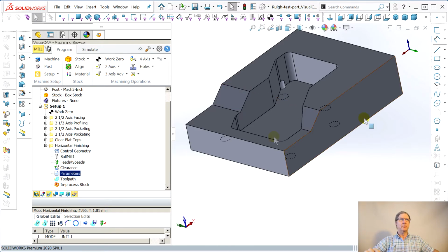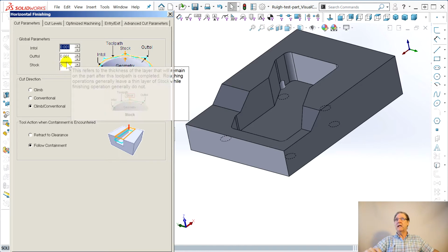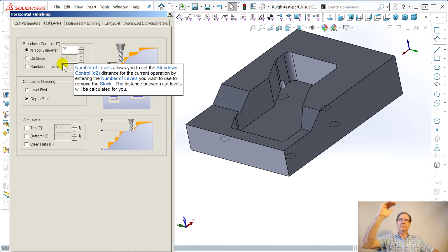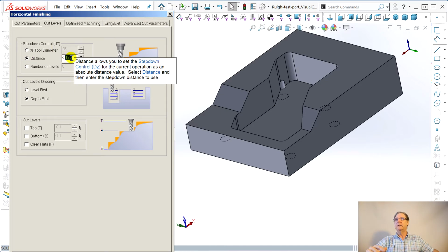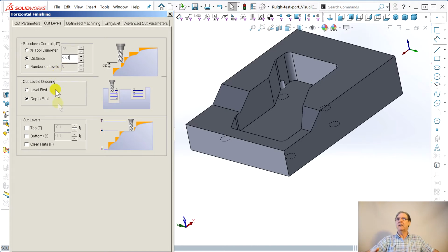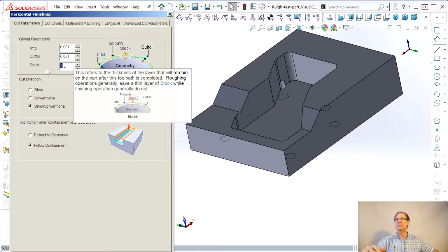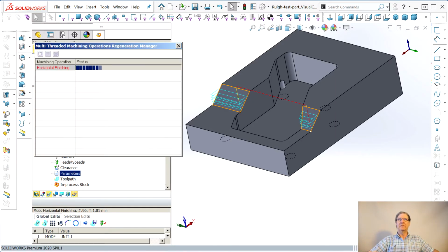So once again, you go to parameters. This we did in SolidWorks CAM, same kind of mentality. It left 0 for the stock. It left tight tolerances, cut levels. Here it's doing 25% of the tool diameter as Z. I don't know why. It's a nice thing, I guess. Let's try a 10,000th of an inch. And let's go back here. See, just because we changed focus, it made this a 1. Scary. I'm getting used to the bugs.